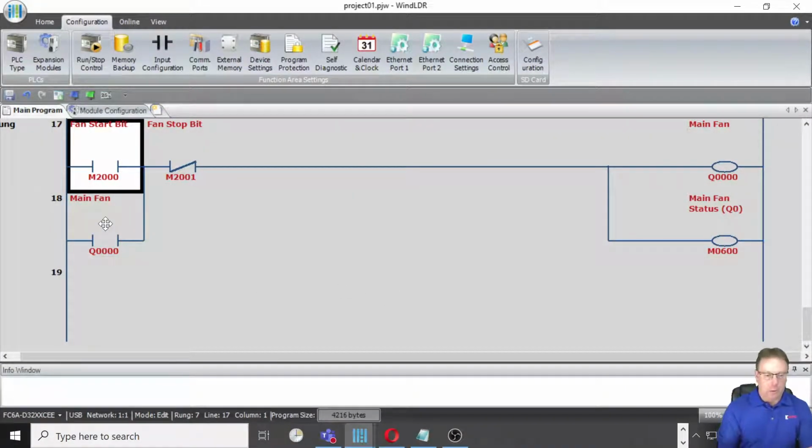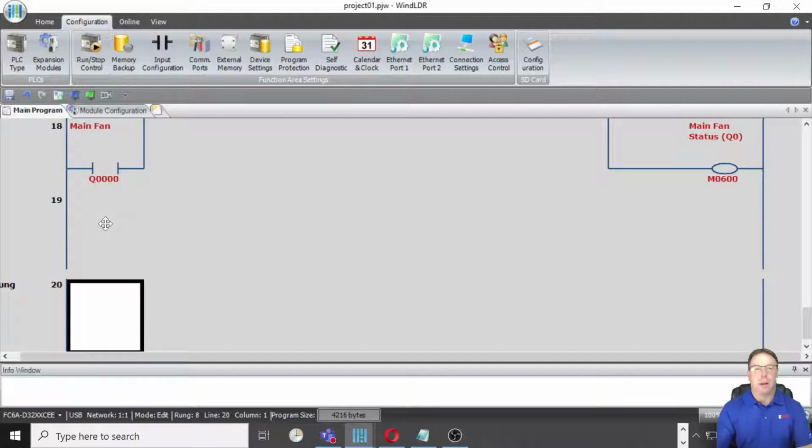And let's hit enter. We're going to add a little logic, but before we do, let's talk about what it is that we want to accomplish. So for this example, let's assume that on the Node-RED dashboard, the numerical input widget that we're controlling is for a PID set point. And we'll say that in the logic, once we receive the value over MQTT, we want to do some comparison, just to make sure that we've got a valid value, and then maybe do some conversion on it before we pass it on to our actual PIDD instruction.